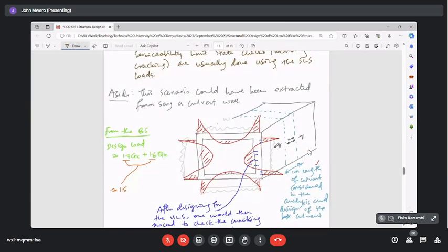There's a bending moment that is trying to bend the wall, and we've put reinforcement near this face to prevent these cracks here. We've put reinforcement on the inner face of the box culvert to prevent these cracks that I've sketched there. So how much stretching is the reinforcement feeling under the current loading, that bending moment that was defined? How much stretching, how much stress is the reinforcement feeling?